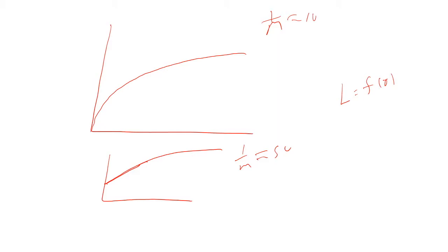If I give you a velocity gradient and ask you to break it up and find the stress, such that the shear rates over all the slip systems, averaged over all the grains, give me this velocity gradient exactly, it's tricky.